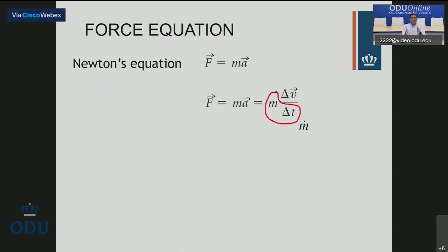And as you could see, they go hand in hand. Force and momentum are related to each other. So I need you to remember this equation and write it down. Force is mass flow rate, which we learned when I explained the 10 burgers idea, times the change in velocity.